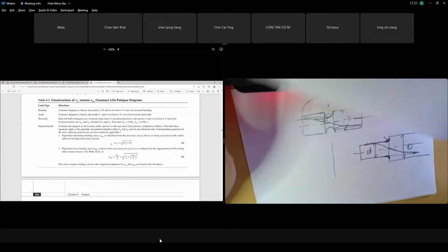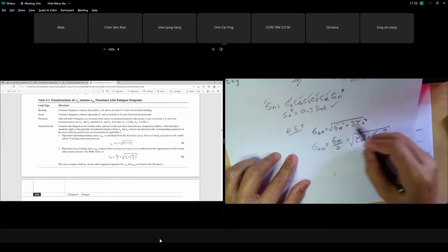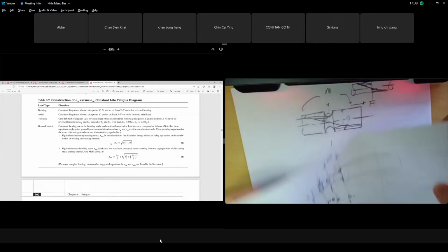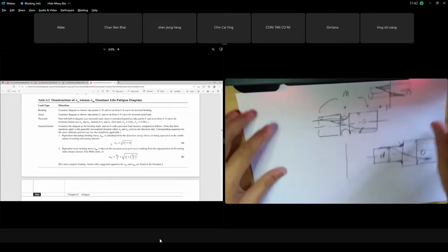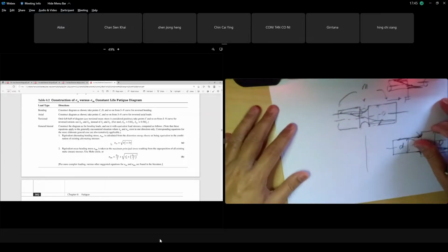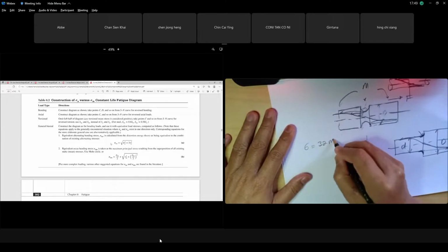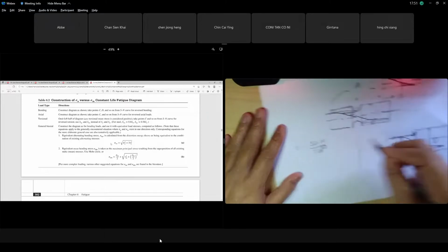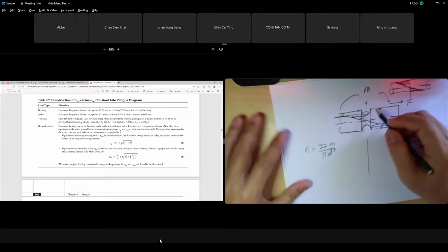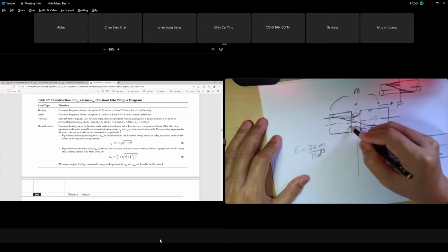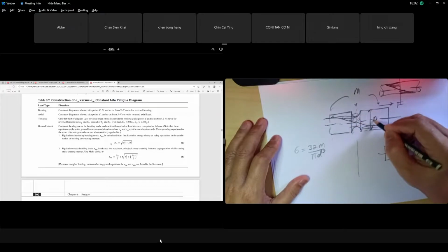So it means that the stress that you calculate, all your sigma amplitude, your bending stress, can you hear me guys? Normally the bending stress we calculate is 32M over pi d cube. In this case, we take the smallest d, because this is the worst case. The inside is the smallest diameter. This one is a bigger diameter.